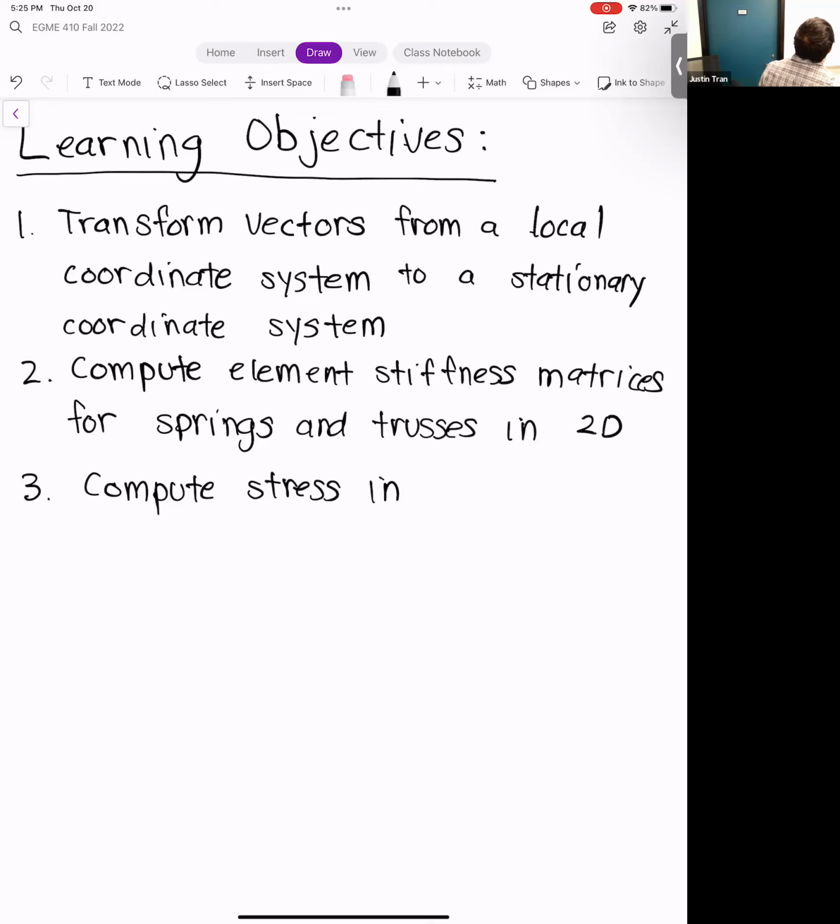Yes. You might not have to, because sometimes when you put an assembly in, it might have that information already, and it might have the contacts. And so you have to see. When you import a part into ANSYS, it'll have a list of contacts that it does automatically. So you're going to have to go through each one to see if those are actually the screws that you did. If it's not there, then you'd have to fit them in. Okay, all right, that sounds good.